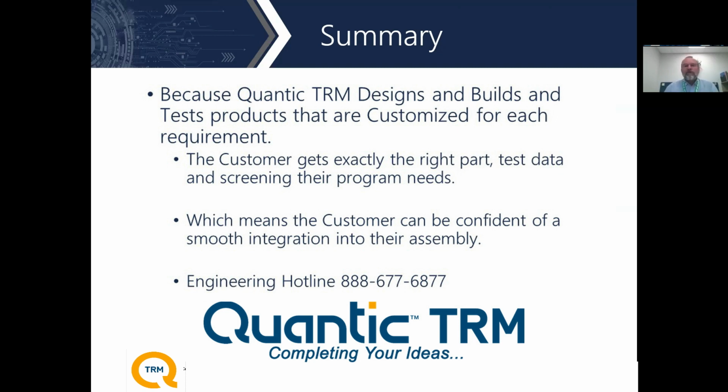That's a good question. Yes, sometimes it does. For the most part, I will say we can use either lumped element, strip line, distributed sort of technology in virtually any package. I think what really limits those sorts of applications has a lot to do with the size. For example, if we're going to a surface mount component that has to handle high power, in those applications a low frequency ferrite type solution will not have enough thermal surface area to dissipate the heat generated, and therefore in that situation, I'll say no, we probably couldn't use a ferrite based device in a surface mount application.